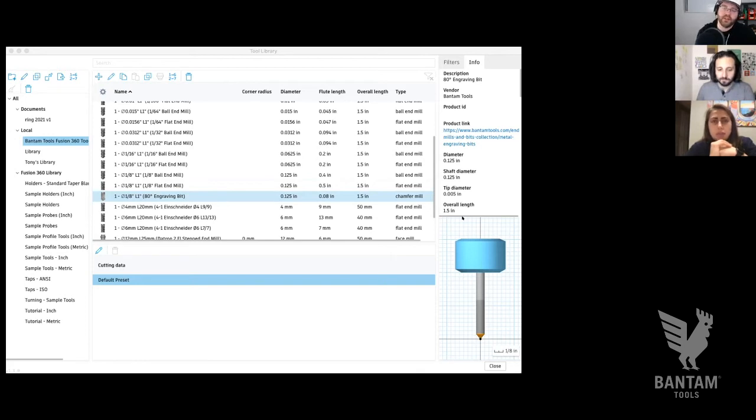And the other things that we'll eventually talk about, and I don't want to touch on yet today, and I'm going to let you get back to Amanda about how we get this information into Fusion. But the other thing to consider is what we're cutting, because obviously we can cut quicker through things like plastic than we can aluminum, because plastic is softer.